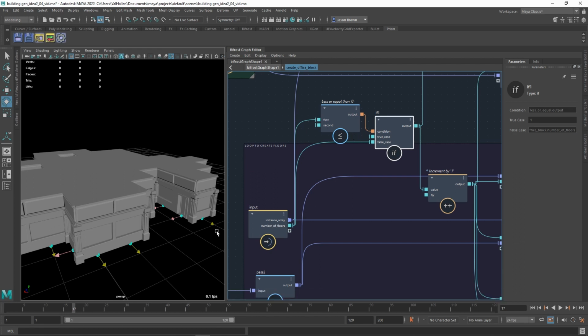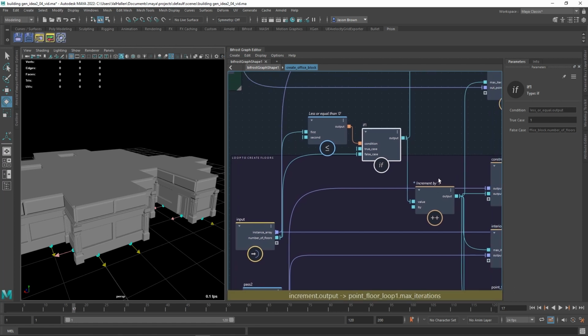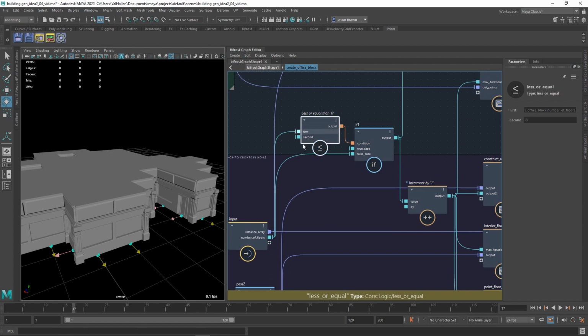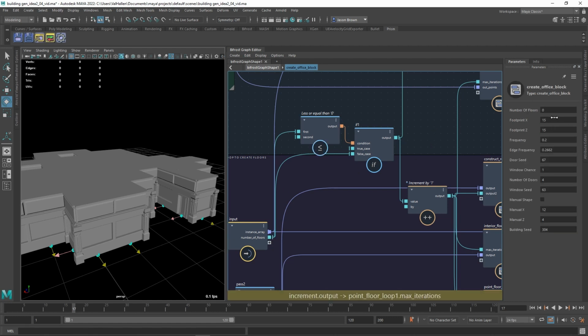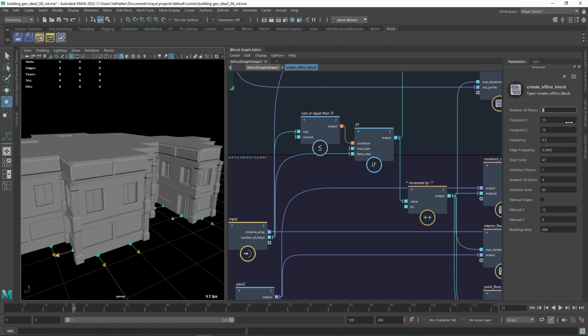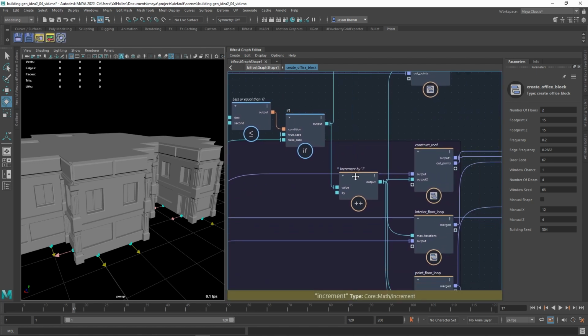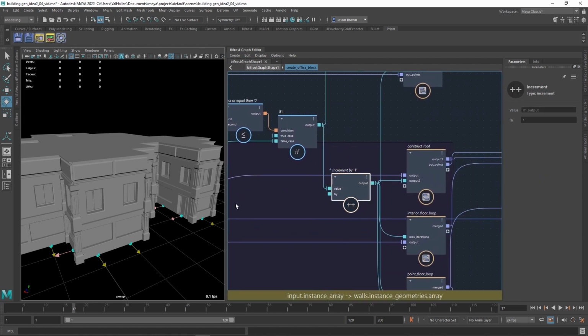We'll just make it 1, so we've got a 1-story building, which is giving us our ground floor instances and our top floor instances. But if it's greater than 0, then just plug in the number of floors. All good. So let's go back up to 2. There we go. Then it adds 1 to it so that basically we can just add this roof on top.